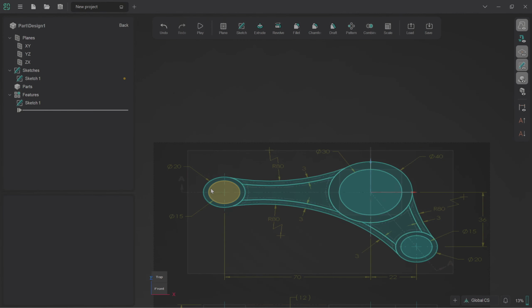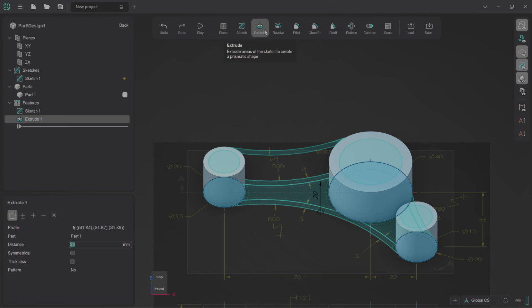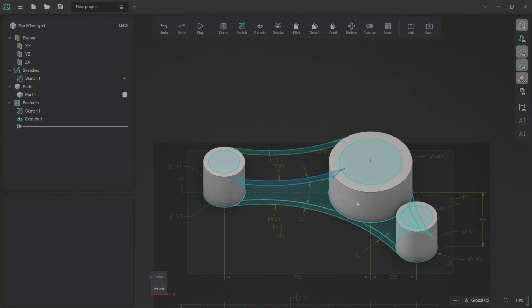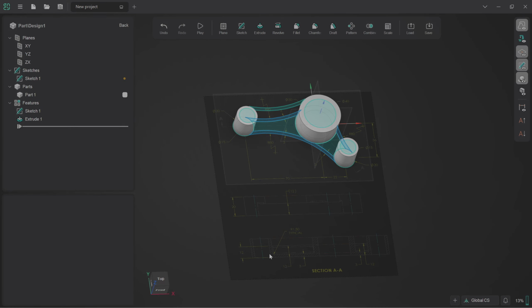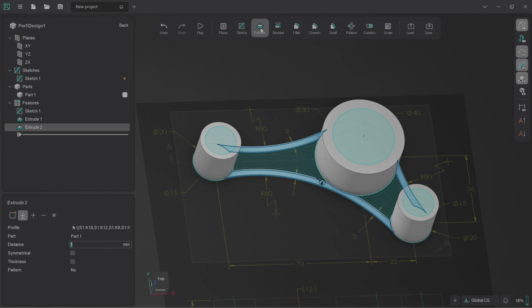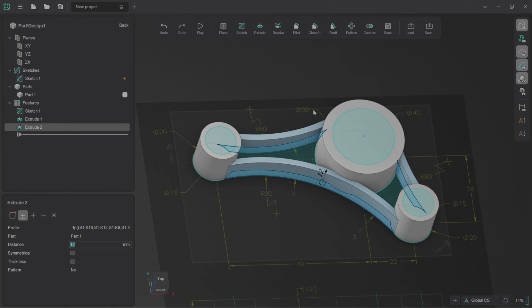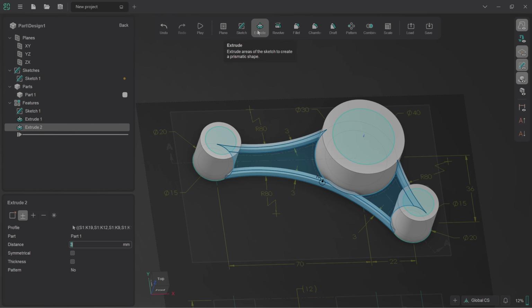And I'm going to start by extruding these cylinders. So let's grab them and we click on extrude and we type in 20mm because that's the height we want them to be at. Okay, that's all good. We grab these wall features and we tell it we want them to be, was it 12mm, I believe? Yep. So extrude to 12, great. And now we grab the base features and we set those to 3mm. Except we don't do it like that because I've messed that up because I hadn't deselected the previous extrusions. Still, it's not the end of the world.